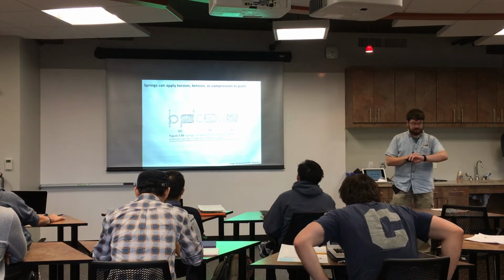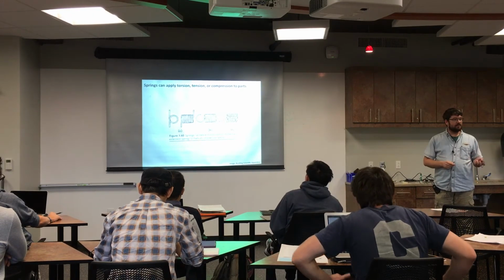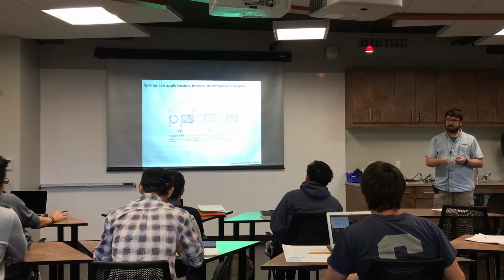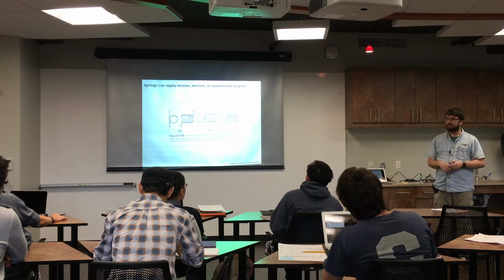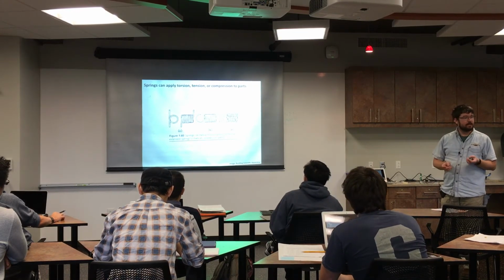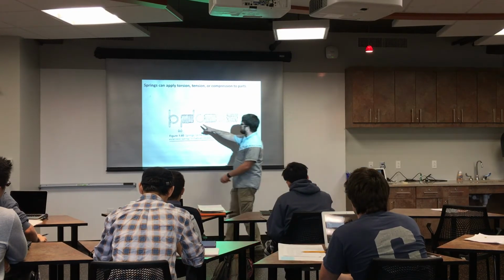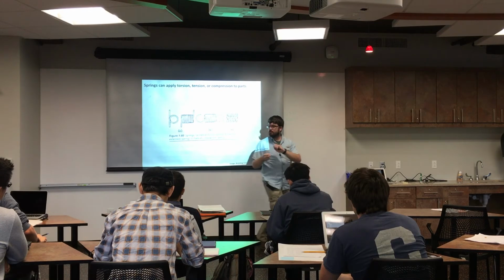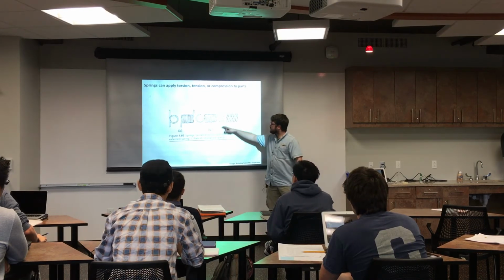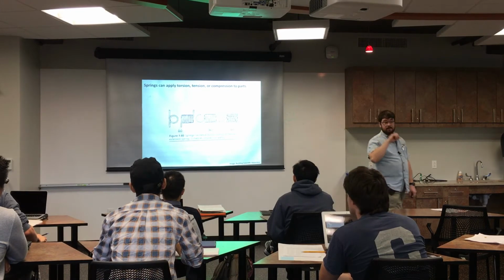Springs, I've got one entire slide on springs because everybody has played with them. But don't forget that they exist when you're doing your designs, because sometimes you're like, oh, I need something to pull this, and you come up with some complex thing when a spring would have done just fine, and it's 39 cents from McMaster. There are torsional springs like this, where you can twist, and they resist that. Tensional springs and compressional springs, and every possible variety that you can think of.